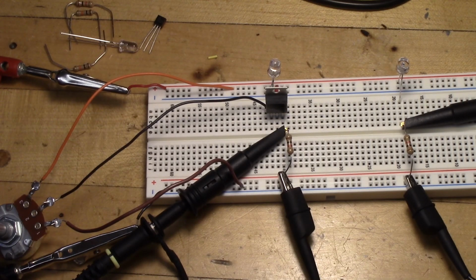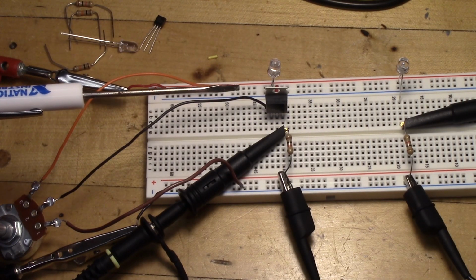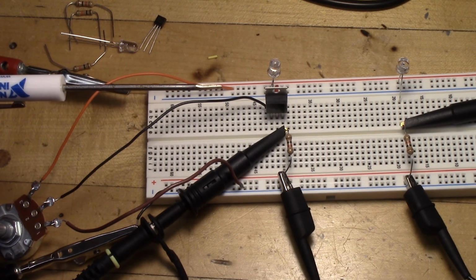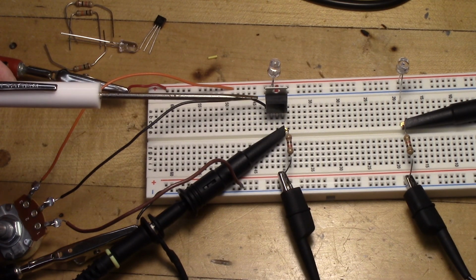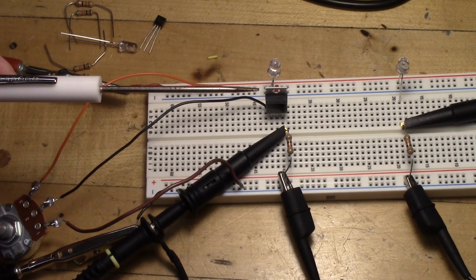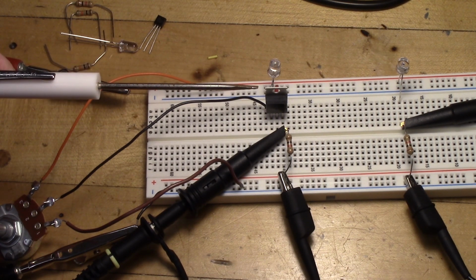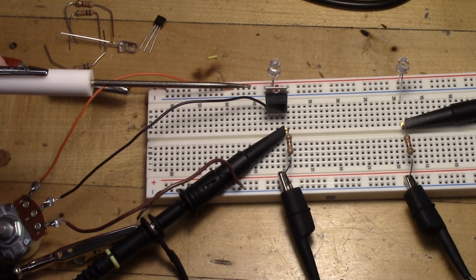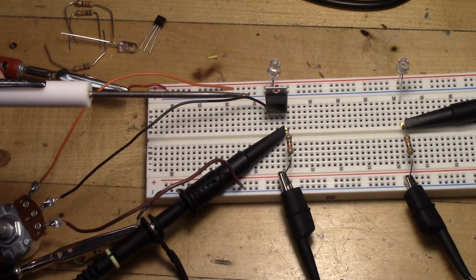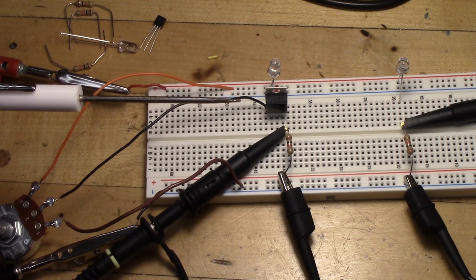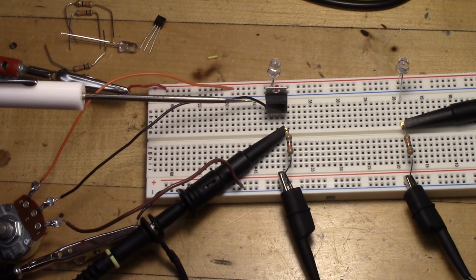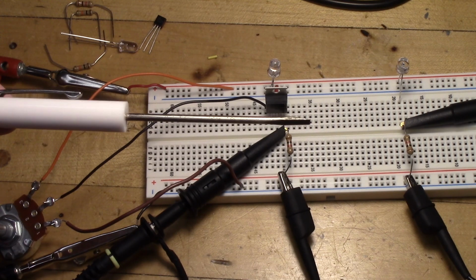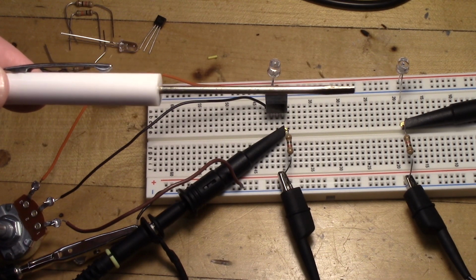Now I can also add a DC biasing voltage to the base to get it to the switching characteristics that I want. Here I've added a potentiometer. The idea is that I want to add a DC bias voltage to the base of the transistor, the same base that the photodiode is connected to. I can either lower the output voltage or raise it. This isn't going to change the amplification, but it's just going to set the voltage level a little bit higher or lower. So I can set this photodiode and Darlington transistor combination to operate a little more closely to the phototransistor.